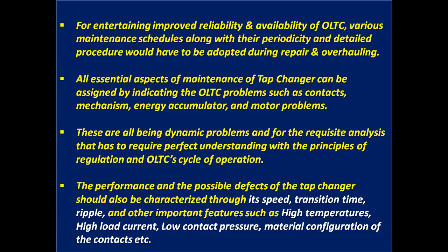All essential aspects of maintenance of tap changer can be assigned by indicating the on-load tap changer problems such as contacts, mechanisms, energy accumulator, and driving motor problems. These are all dynamic problems, and for the requisite analysis, perfect understanding of the principles of regulation and OLTC's cycle of operation is required.